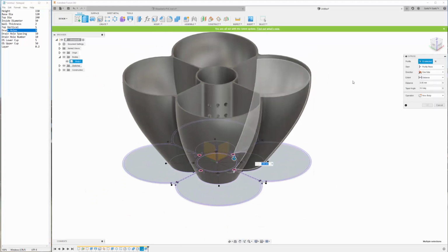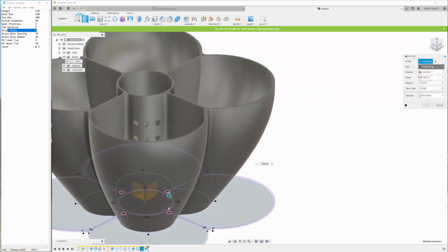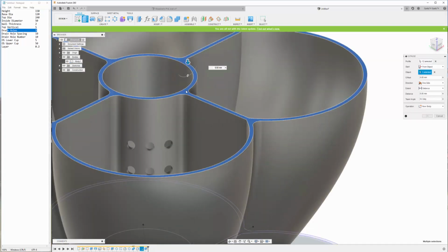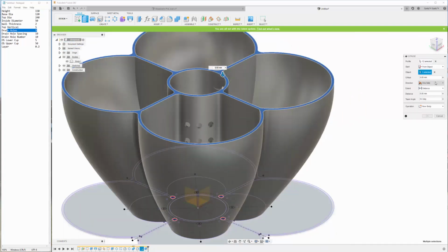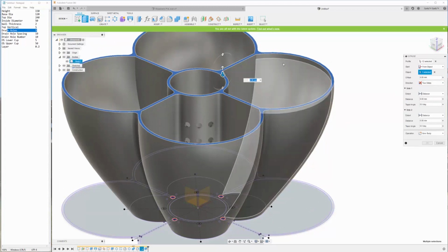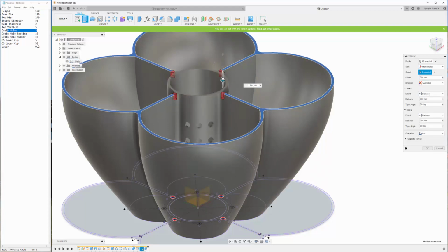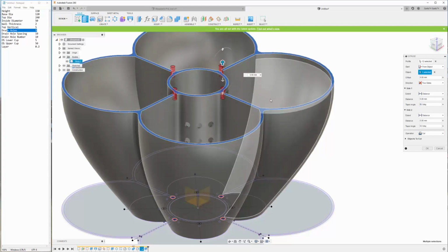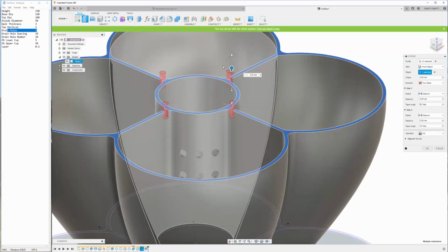So now if I hit the extrude, instead of starting from profile plane, I'm going to say from object. Now I can select that from the object direction. I'm going to go 2 sides. And what I'm going to do now is project this down, so I can go, well, that's 5 millimeters. But this time I can say I want it to go up 5 millimeters as well.